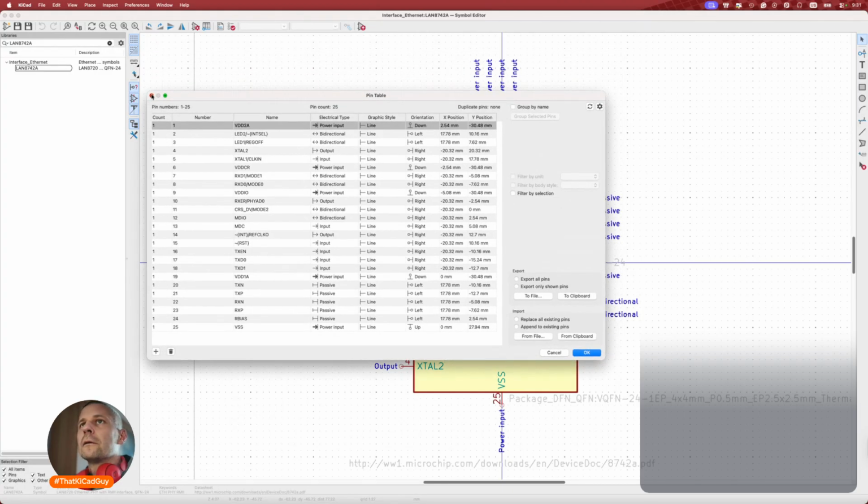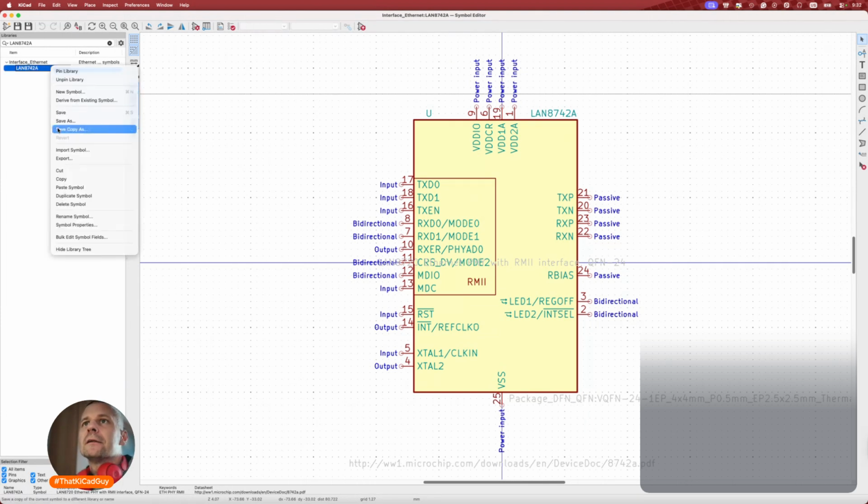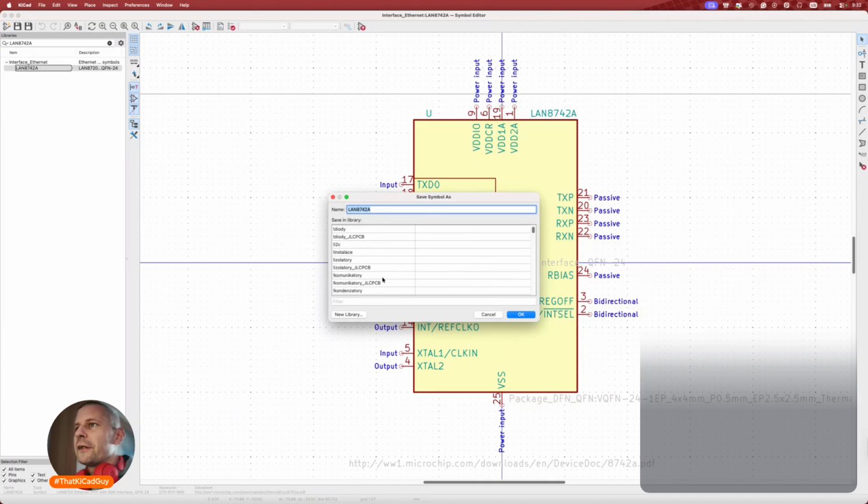Yeah, I forgot to check the DDR3. Should I? Yeah, probably yes, but maybe later. I'm lazy. All the memories are under the JEDEC consortium, and the pinouts are controlled by the standard, so usually it works. This is why all your SPI flash memories have the same pinout. This is the same as the standard logic, the same as op-amps. Yeah, not all the op-amps, but the standard ones share the same pinout. This will be the case as well.